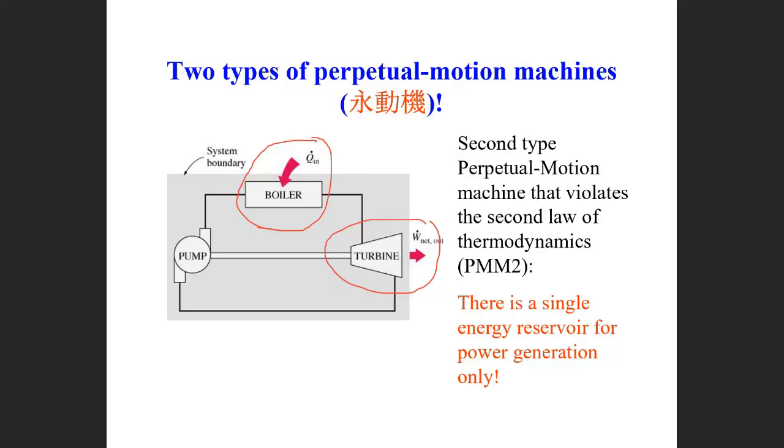So in history, many people tried to invent perpetual motion machines. They think they can make the efficiency 100%, or that they don't need any input but still produce work. It's impossible. They violate the first law or second law of thermodynamics. So we understand that according to the second law, any process has its direction, and when energy is transformed, some energy will be permanently reduced to a lower energy value.